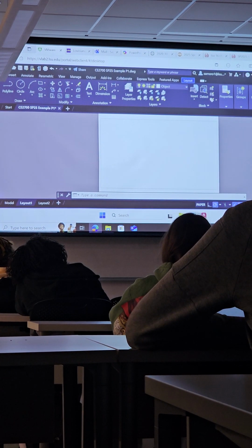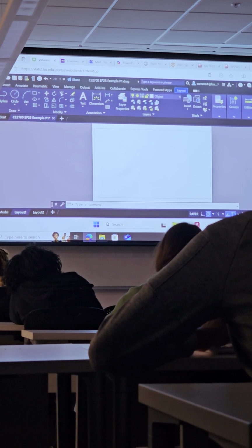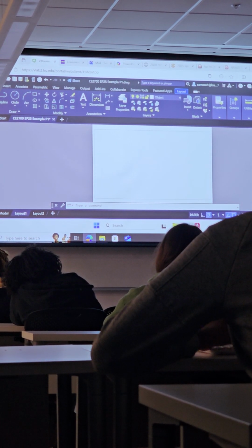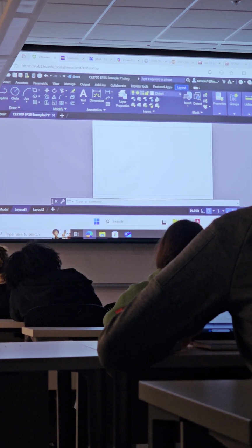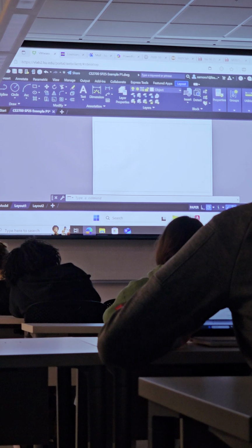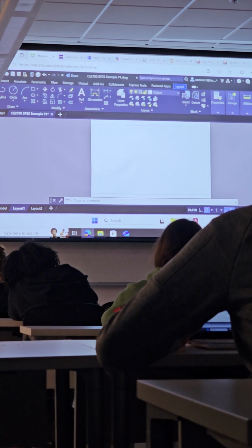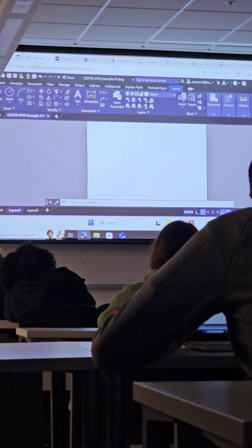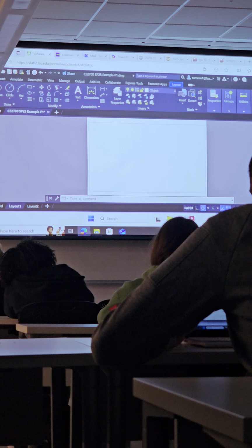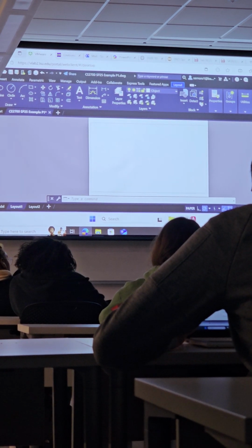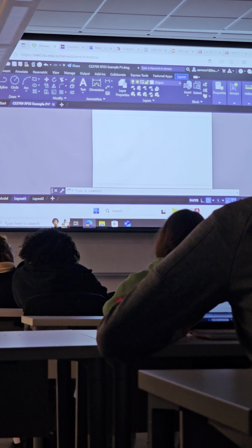When you're in the Layout tab, you're going to use a command called xref. That means external reference. One of the most powerful capabilities of CAD is to show the contents of some other file in the file you're in. So imagine you're producing a set of plans that is this thick, right? It's got lots and lots of drawings in it. The title block looks exactly the same on every sheet, except for a few pieces of information, right?